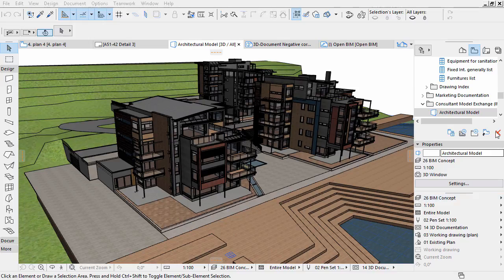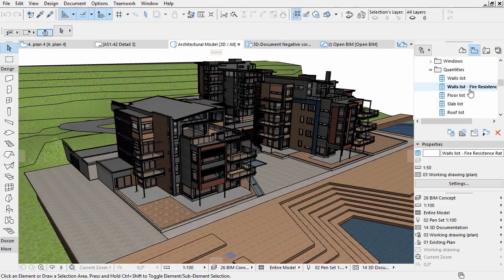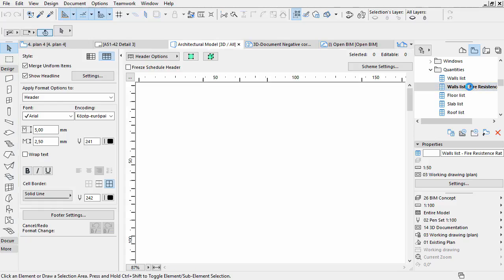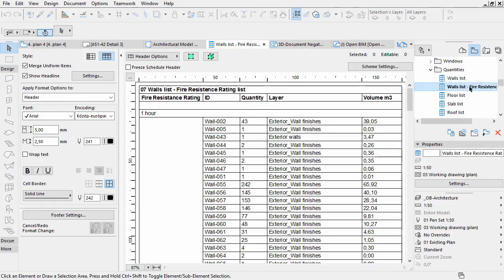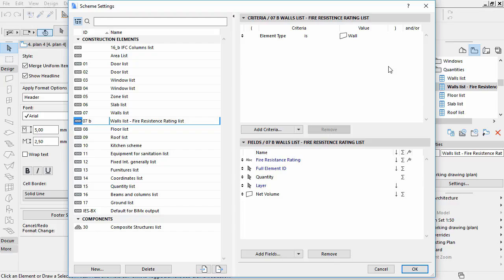At any phase of the project, we can use interactive schedules to create schemes and lists of existing and imported elements. These schedules can be saved in spreadsheet format. For example, list the project's walls by quantity and fire rating. This schedule summarizes the major properties and quantities of walls having a particular fire rating. It's refreshed automatically if any element is modified.